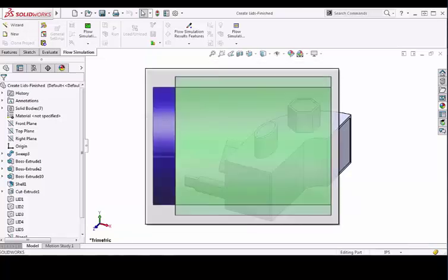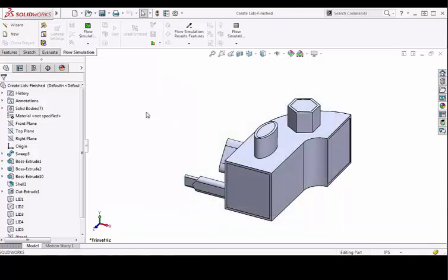However, in this example, created using a blind extrusion, notice that the lid only maintains a line contact with the part. This line or edge contact is incorrect. The lids must have a surface contact in order for the flow simulation to be run. A great tool you can use to verify your lids and setup before creating the flow study is by running